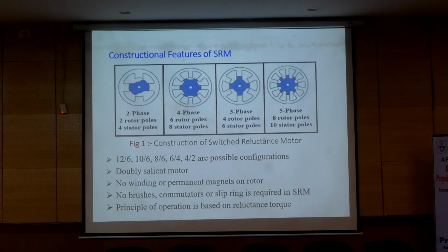But there are some other complexities. This needs a very systematic control with rotor position feedback. And the estimation of this rotor position angle is one main important task that we need to do, the rotor angle estimation. Accordingly, the switching pulses can be developed or realized.